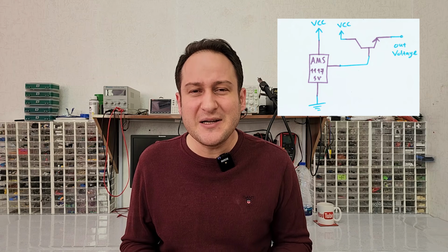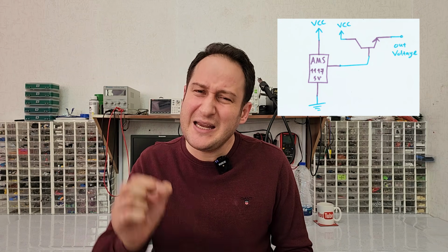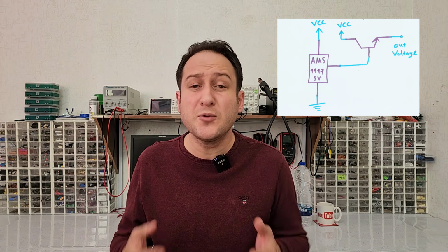Or even you can use this configuration to increase the output power of a tiny and simple regulator up to several amperes and so on. You just need to connect the base terminal to the weak signal, the collector terminal to a high and strong input voltage, then your strong output signal will be ready at the emitter terminal.